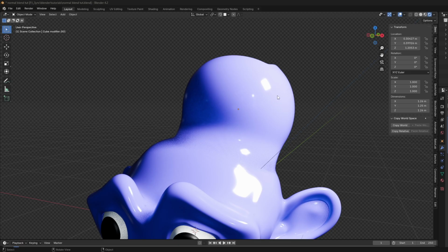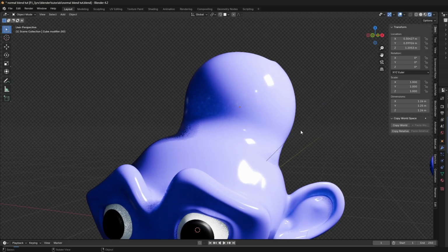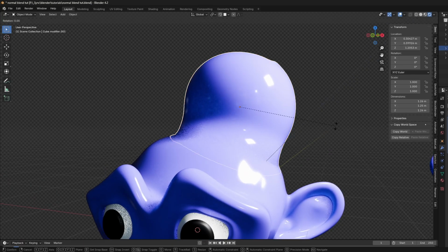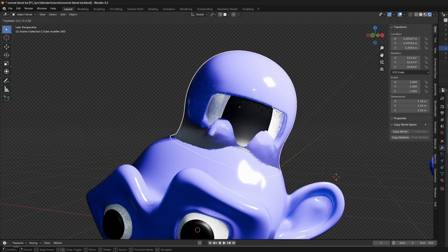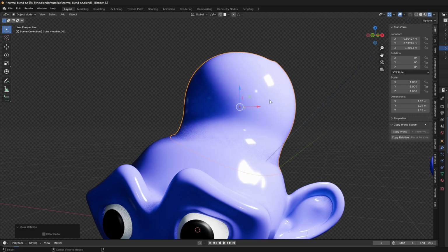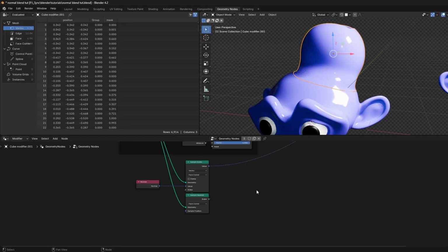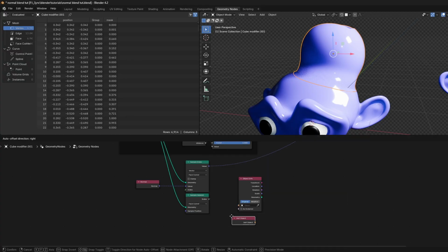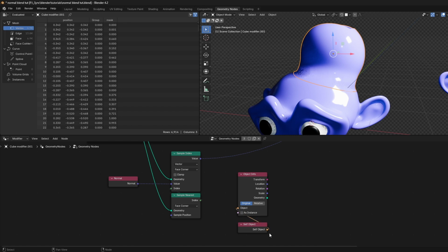There's actually one issue I didn't talk about, and it happens when you rotate this object. You can see if I start to rotate it, the connecting point, the normal doesn't really line up. So you actually just have to do one thing in geometry nodes. We can just get an object info node right here, get the self object, which means we have access to the location, rotation, and scale of this object right here.